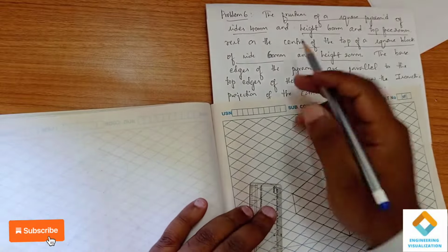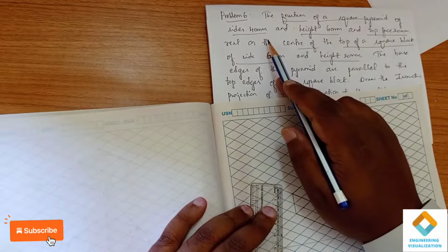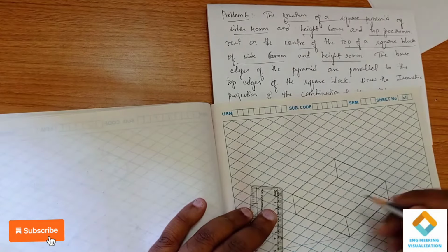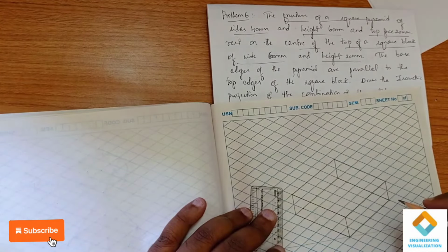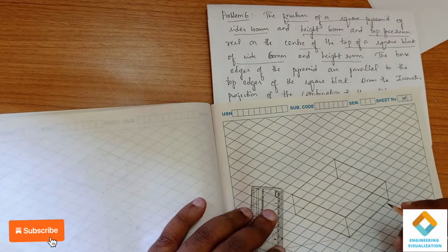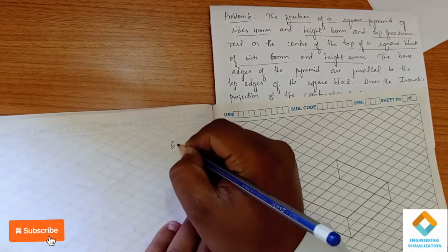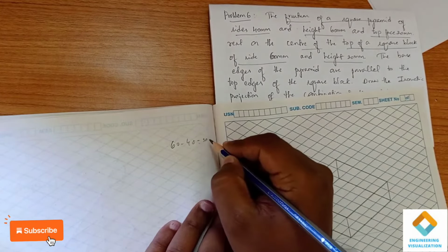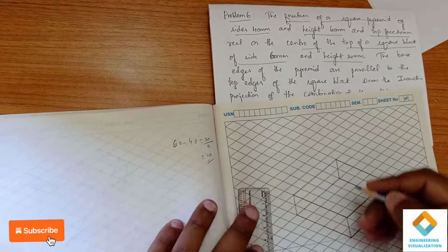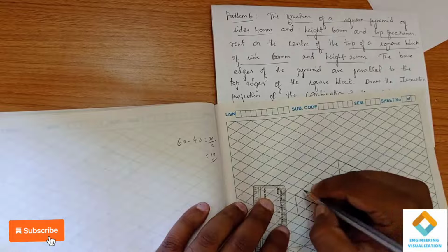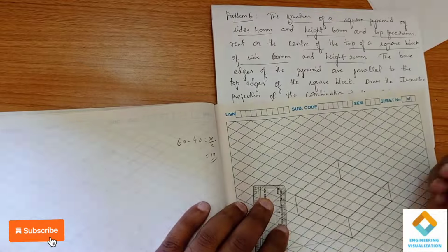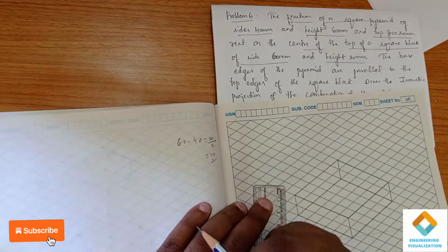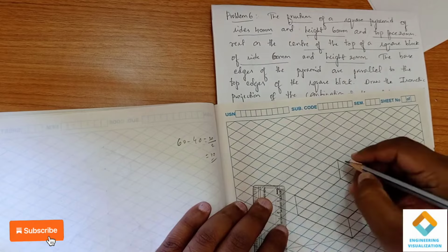Now you see that we have to construct a frustum of square pyramid with base side 40, height 60 and top 20. So we need to get a square of 40 here, but here we have 60. So how to get the 40? Herein we go for the subtraction of the box method, that is 60 minus 40. The base we have is 60, we require 40, so it means 20. 20 by 2 means it is 10. So we need to subtract by 10 mm on each side. Okay, so 10 mm means one box distance. Okay, understood. So 60 minus 40 is 20, on either side being divided by 2, so it is 10. 10 means one box, so we need to subtract by one box on either side.